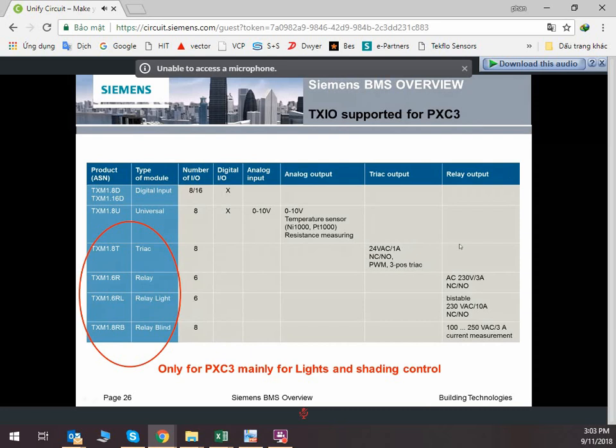Okay. By the way, the DXR E10 is actually for on-off control, and then E9 should be for modulating valve control. So E10 uses triac output, so you might need a relay for your on-off. Okay, so if you have difficulty to program it, we will discuss offline.